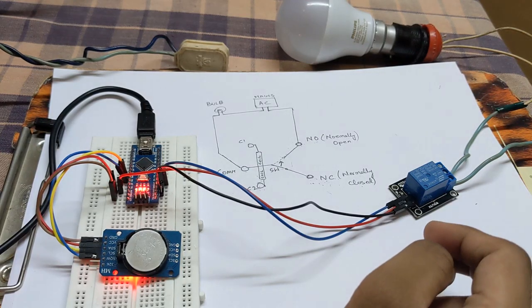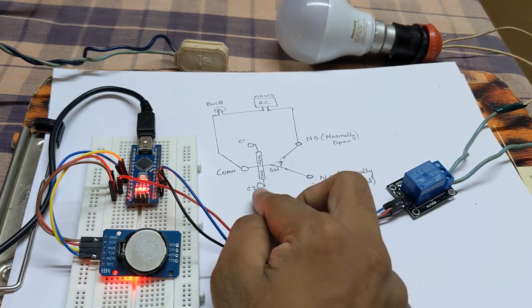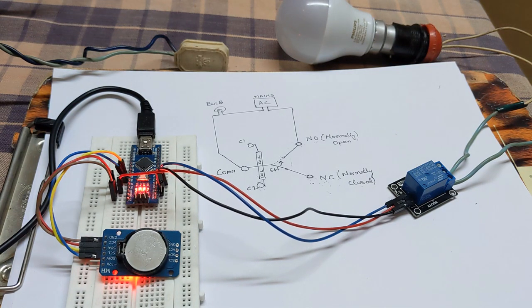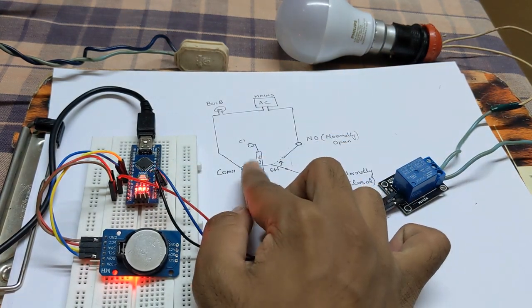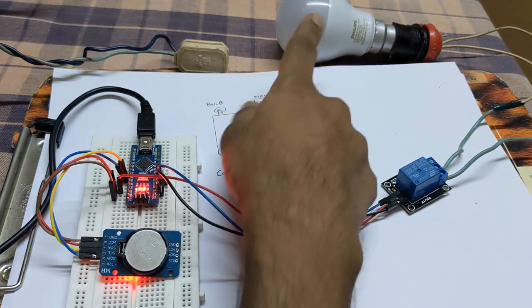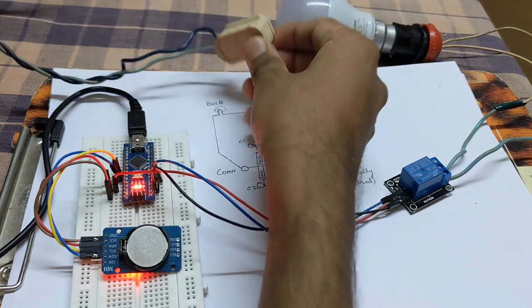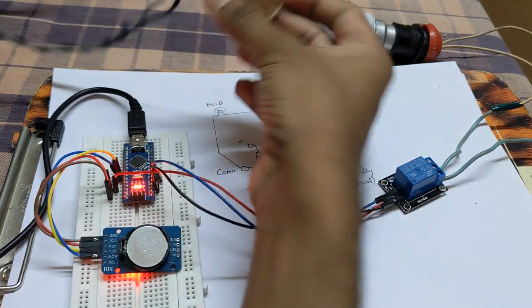Okay, so we'll try to make a simple project using the relay. I made the connection like this. We are trying to make an automatic night lamp, so that at a particular time the night lamp will automatically turn on. For this we are using the relay, and I made a circuit as shown in the figure here. This is a light bulb. One end of it is connected to the plug and the other end to the COM, and then from the NO it goes again to the plug.